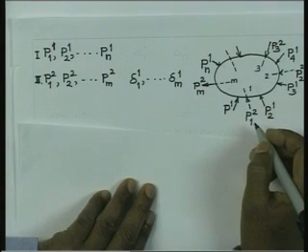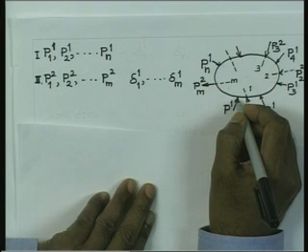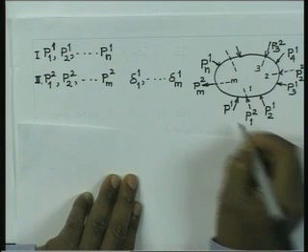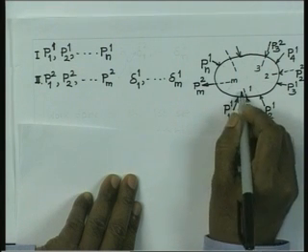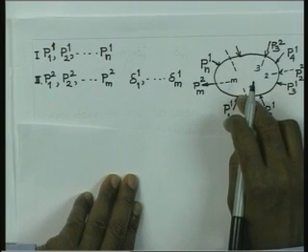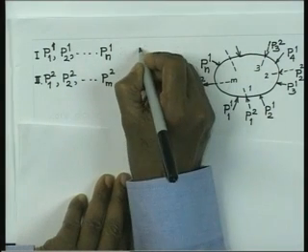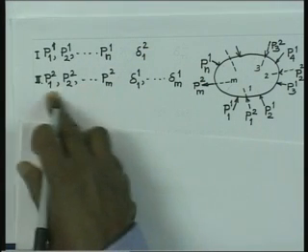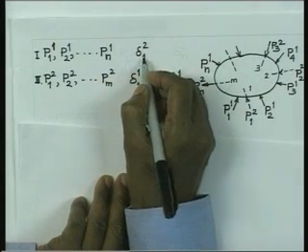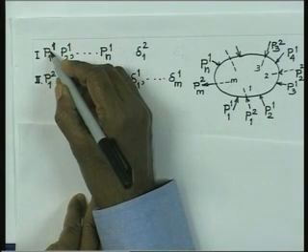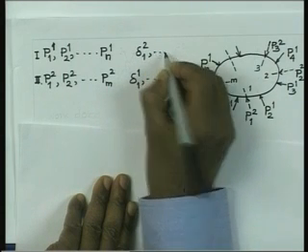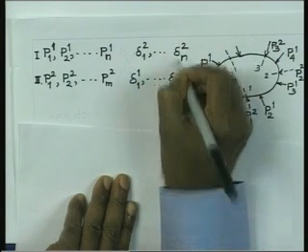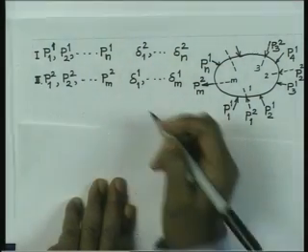Now, if I try to see the deflections along the line of action of the earlier force P11, so this is the force P11, let us say that the deflection in this direction is delta 1 superscript 2. So, this force set produces a deflection of delta 1 superscript 2 along the line of action of P1. Similarly, we will have up to the nth force, and the deflection is delta n2.